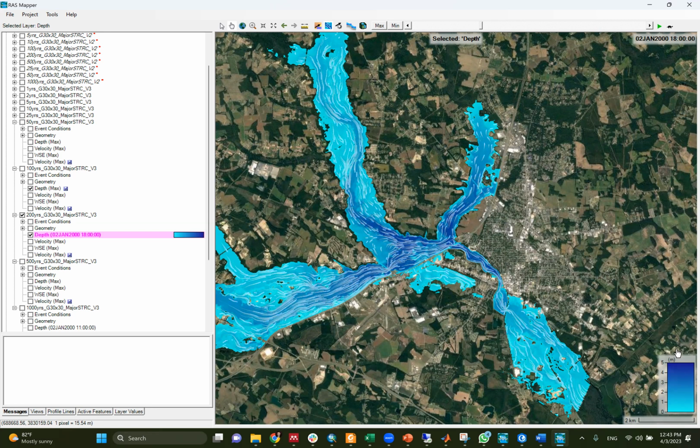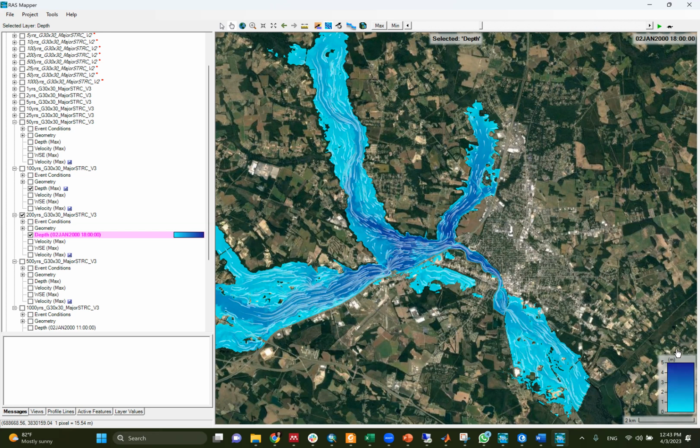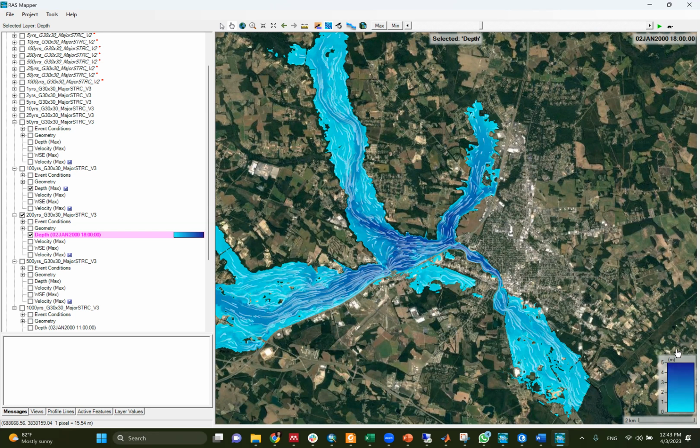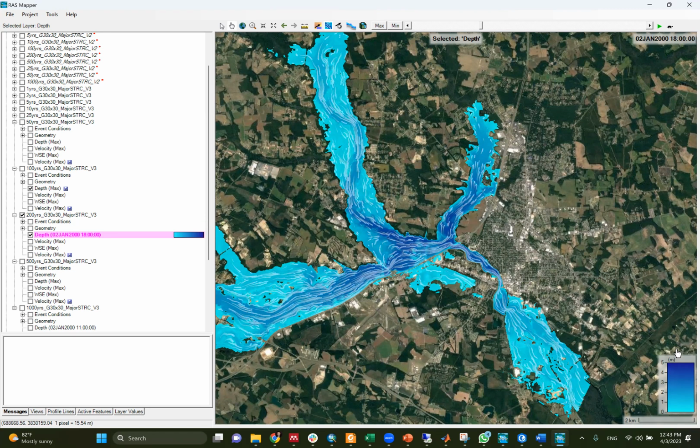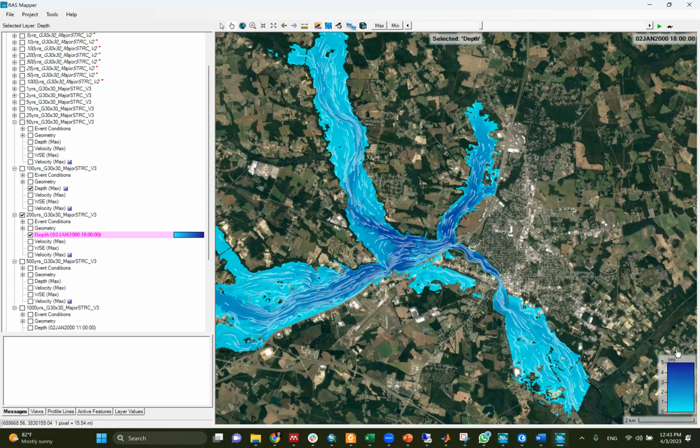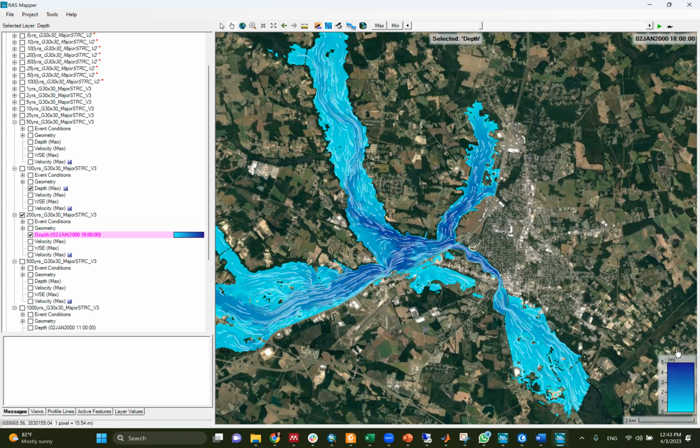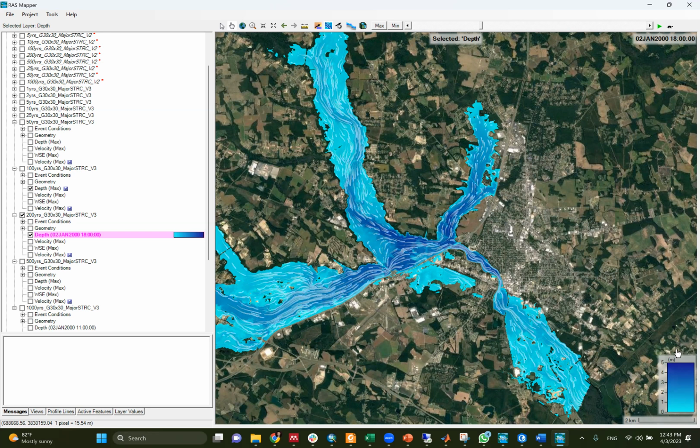Okay, so step by step, I'm gonna list them in a Word file so you don't forget. So you will have hazard, exposure, vulnerability, do some GIS work to identify the flood depths at each building, and then take the flood depths for each building in MATLAB. You read the shapefile, you run the vulnerability function, and get damage in terms of losses and exceedance probability of each damage state. So right now we are done with risk analysis, like basic risk analysis without any mitigation.